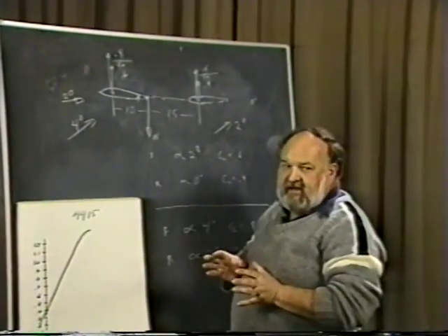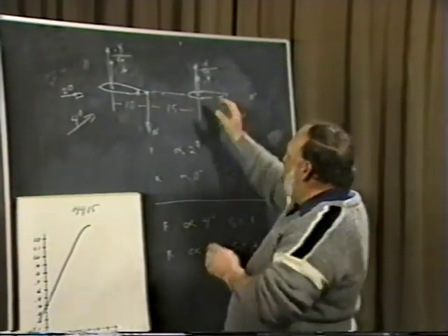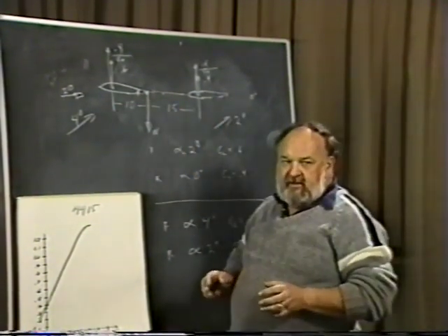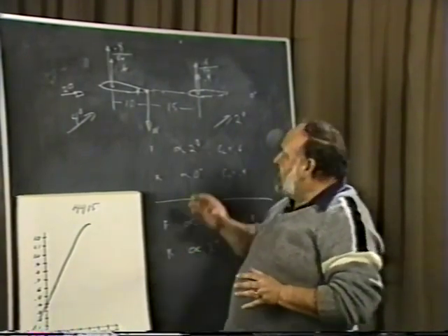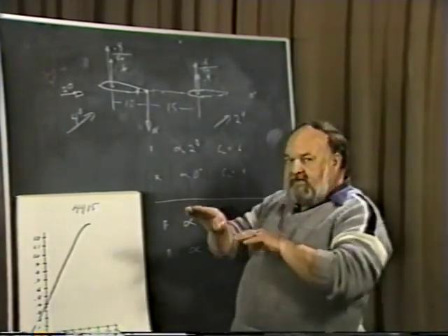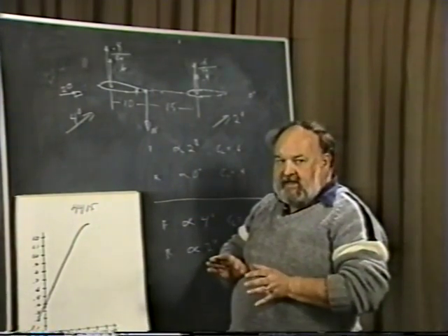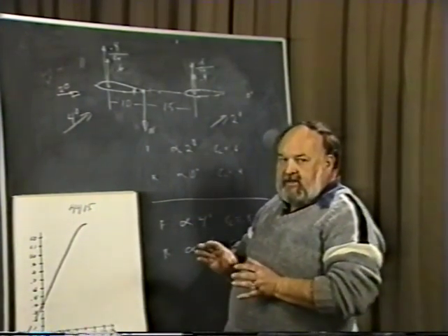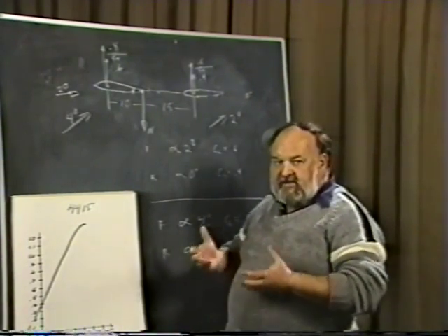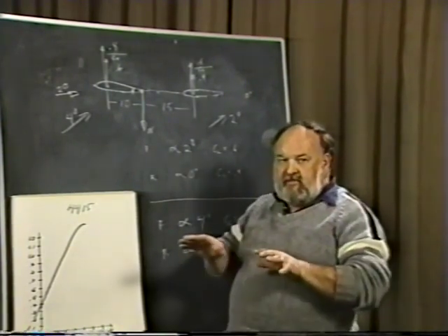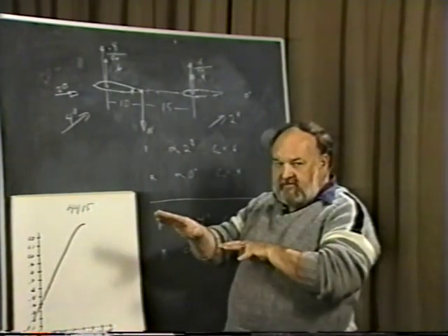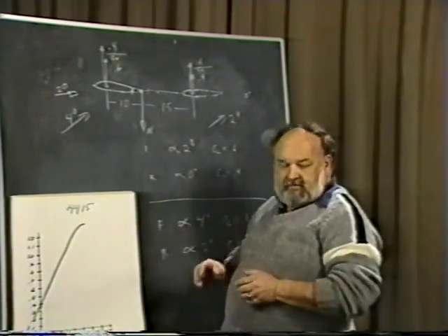What you really have to have is a balance between the front surface and the rear surface in such a manner that the rear surface, because it is at a lower incidence, will have a lower angle of attack. It will generate a relative or percentage increase of lift with the same change of angle of attack of the two surfaces that is greater.